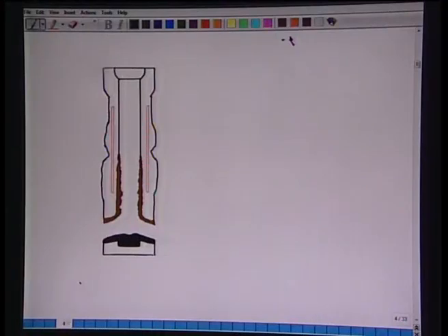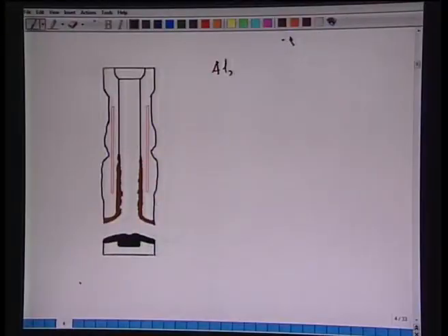Now, another important example that I can show you is the immersion nozzle which is used for continuous casting of molten steel. From the tundish, the liquid steel enters into the mold, and this is being done by nozzles, and these nozzles are made of Al2O3-C, the immersion nozzle.